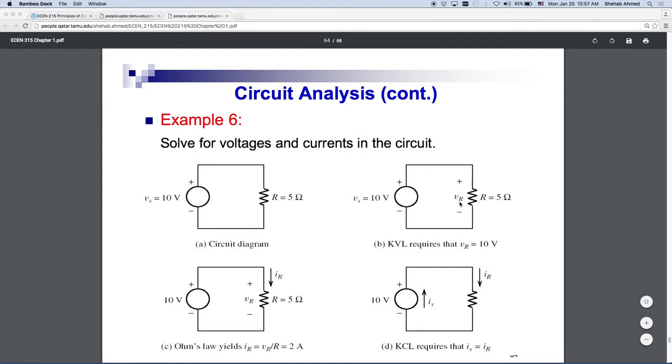So you define your polarity of voltage across the resistor. We know the resistor is an element that only dissipates or absorbs energy. So if you go to our passive sign notation, right, we said that the resistor, or an element that absorbs power or absorbs energy, will have current flowing into the positive node, right? So I can now draw I_R flowing into the positive node this way. And then finally,